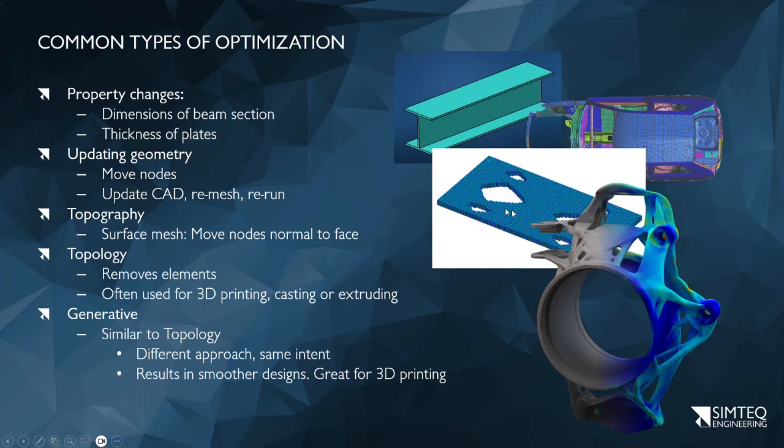And one of the main differences between these two is that in this one, we start with a fixed mesh, and I can't remesh it as it progresses. This one, the way that it works, it automatically smooths it every step, so we actually get better stresses. There we'll have these really high stresses in the corners, making topology kind of difficult for stress optimization. While in this case, since it's smoothed, we get better stress responses. It also allows, as it progresses, since there's lots of material removed, it can now say, but in this region, let's use effectively smaller elements. So it goes through these multiple refinement processes.